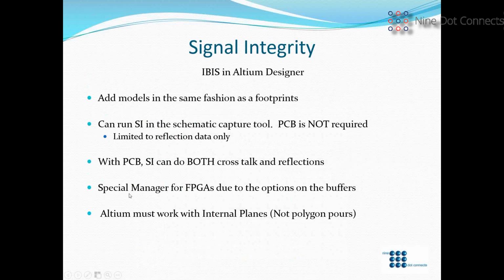And then there's also a special manager for FPGAs. So keep in mind with FPGAs, the user gets to control the buffer types, like the technology for the buffer types, the slew rate for the buffer types, the current capabilities of the buffer types. So unlike other ASICs where those are fixed, the FPGAs have options. So Altium provides you a special tool for that.